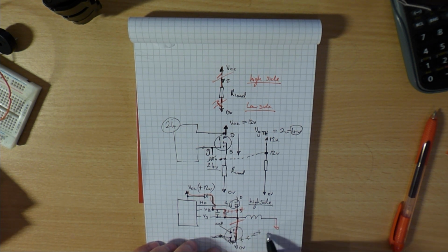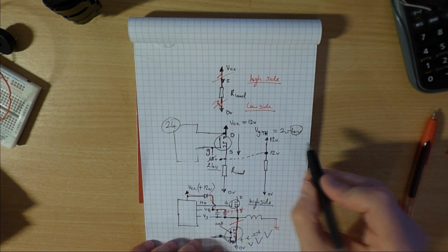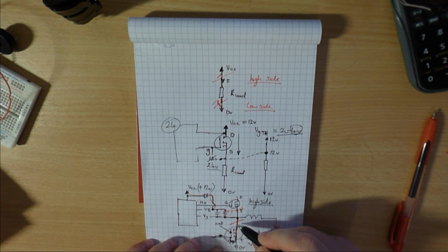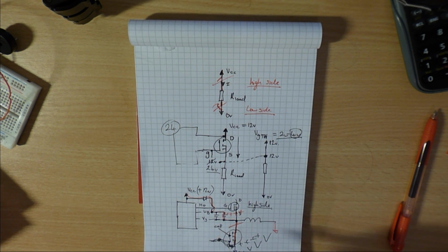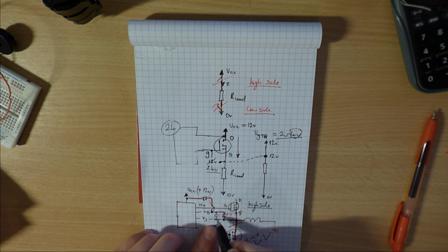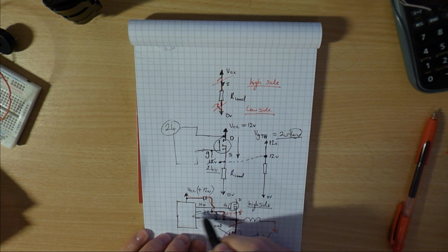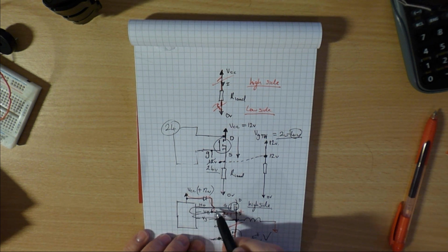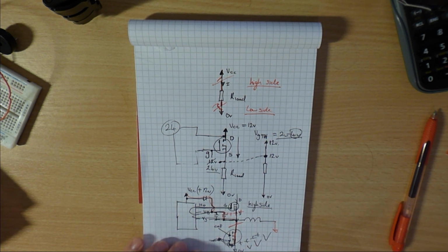And then as the charge builds up on it, so does the voltage, and once the voltage exceeds the threshold voltage that we spoke about here, you'll turn your MOSFET on. That's basically how they work. And that's the reason to have these capacitors here, is so that you have enough charge stored that you can quickly, and that's really the key here, is you can quickly discharge that capacitor through H out to the gate here and turn this on as quick as you can.